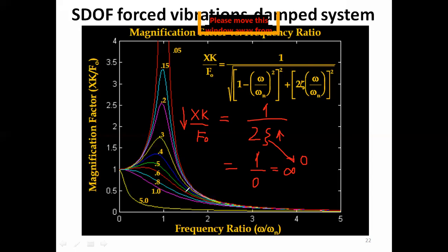It just reflects that under this condition, at resonance, the magnification would be large, but it is not in a position to calculate the value for you. So the problem is in the model. The model is not capable of giving the exact value at resonance when the damping ratio is 0.